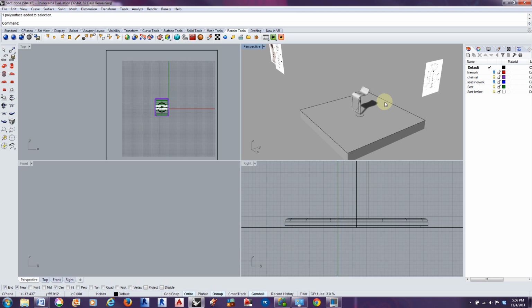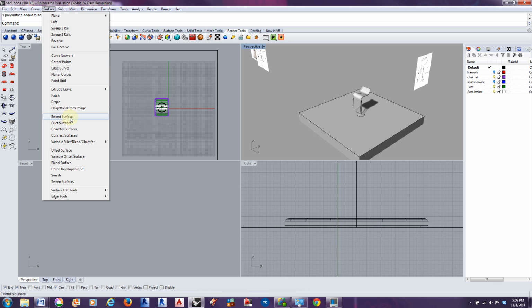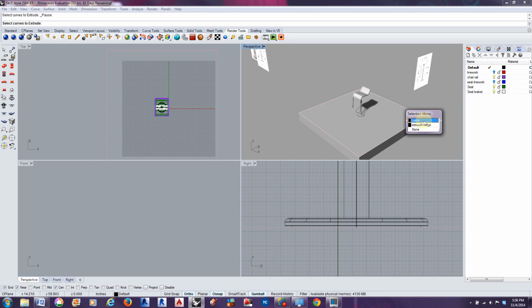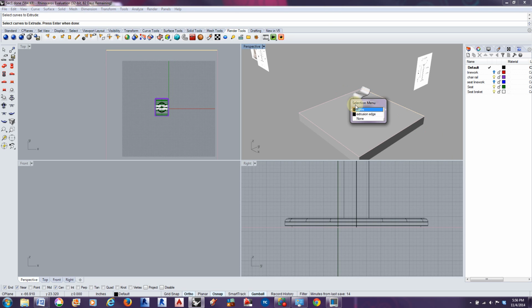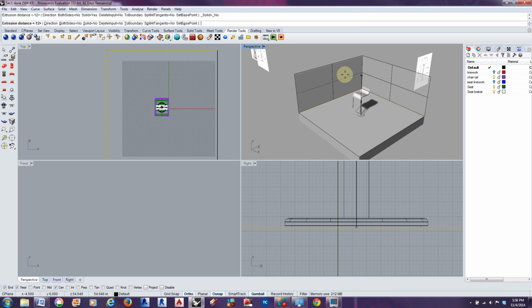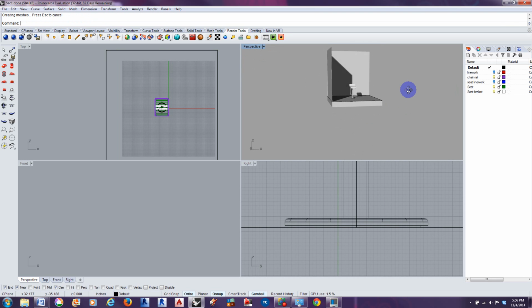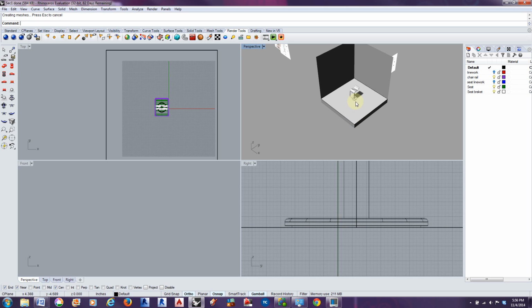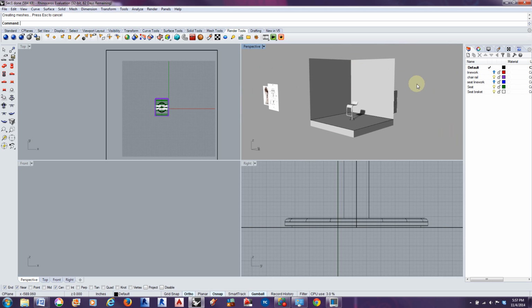And now I want to do some quick walls, and so the way we could do that is utilizing our surface extrude curve straight, can actually start picking the extrusion edge. You could probably pick both of those edges at the same time, and I just typed in 120 for 10 feet. So I'm starting to create a small scene, kind of like just a play scene, right?